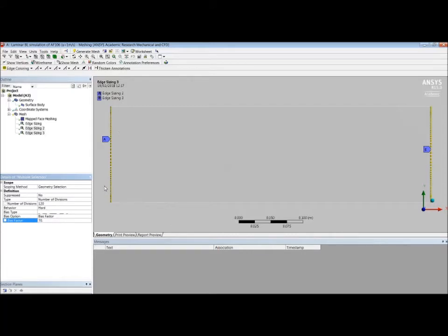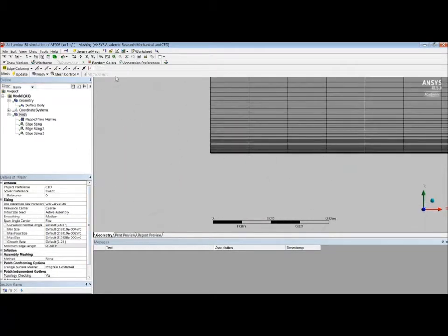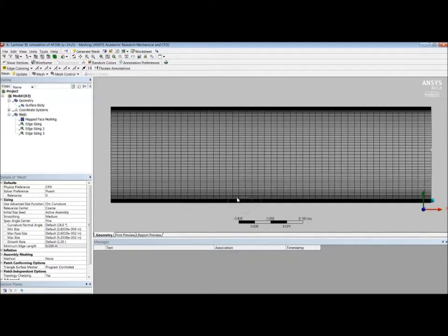All right, now you can really see the distribution of the elements changing. That makes the elements very fine in the near wall area, and that gives you almost this black band, which is very fine meshes close to the wall, which is important for when you're trying to capture the boundary layer development in that area. So what do we need to do next?